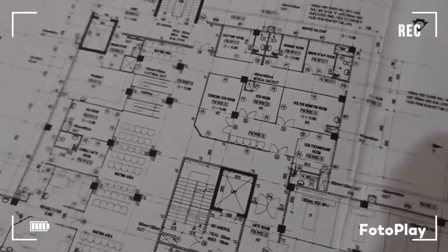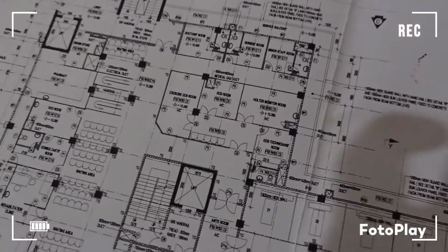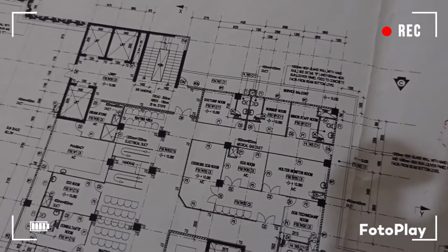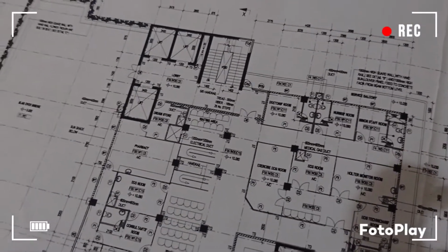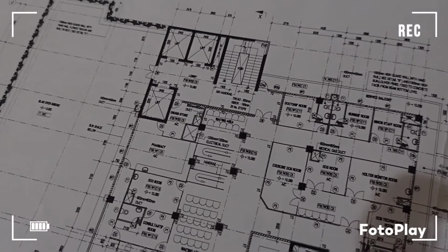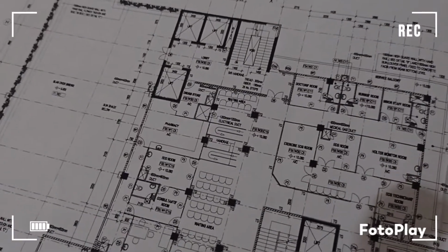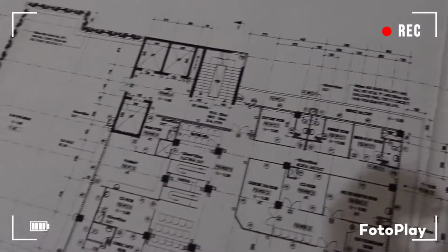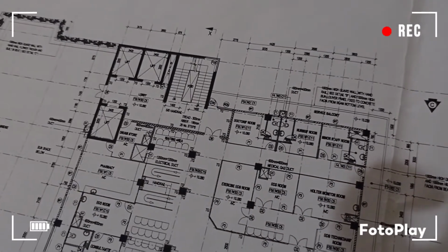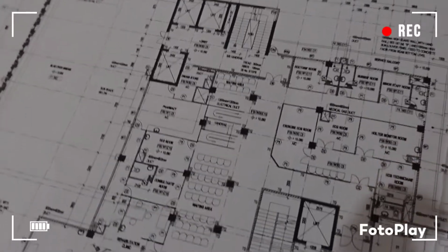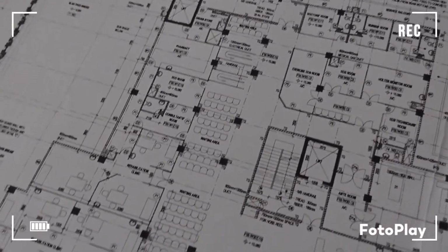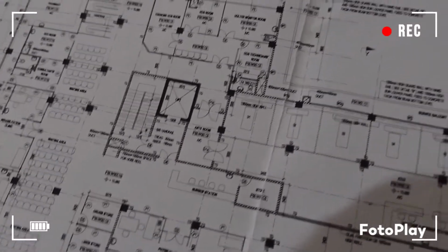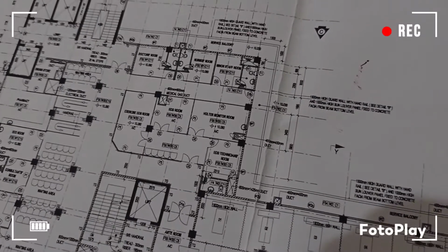Today I am going to tell you about the structural form. In order to arrange the structural form, we should have the architectural design. Now, architectural design shows the utilities and the appearance of the structure, but by thinking about the load path, where to transfer the loads to the earth, you have to decide where you should arrange the structural elements such as beams, columns, or frames, and whatever it is.